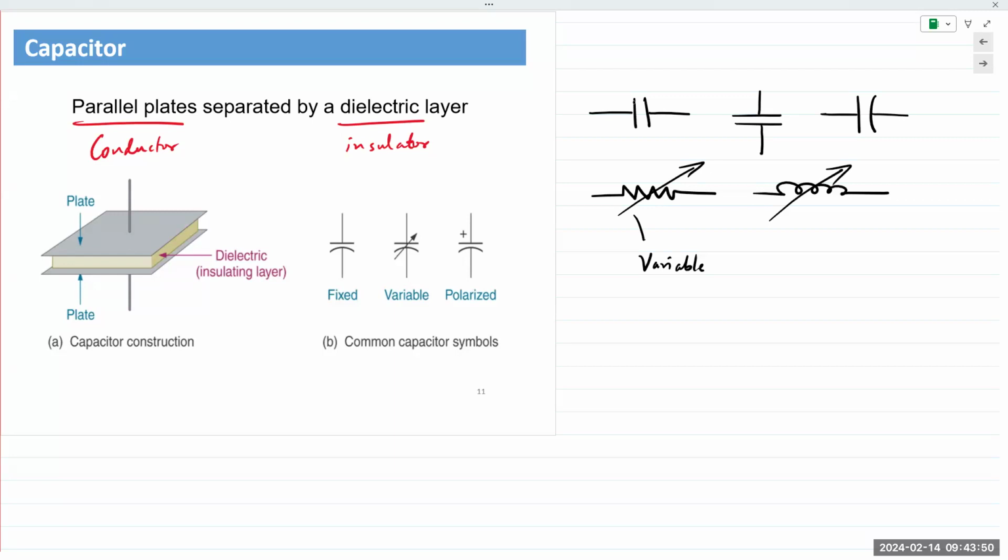So it's a passive component that follows the passive sign convention, meaning current always goes from high to low. Current will always go from plus to minus. If you're given the voltage, then you get the current, and if you're given the current, then the point of entry is plus and the point of exit is minus.